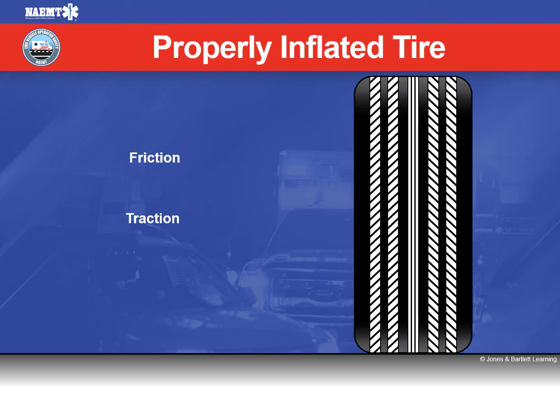It is extremely important, class, to regularly check and maintain proper air pressure. Proper tire pressure is based on the vehicle manufacturer, not the tire manufacturer. The tire pressure should be checked when the tires are cold. That's when the vehicle has been sitting for a while. A drop of just 10% of tire pressure is enough to negatively impact the fuel economy.